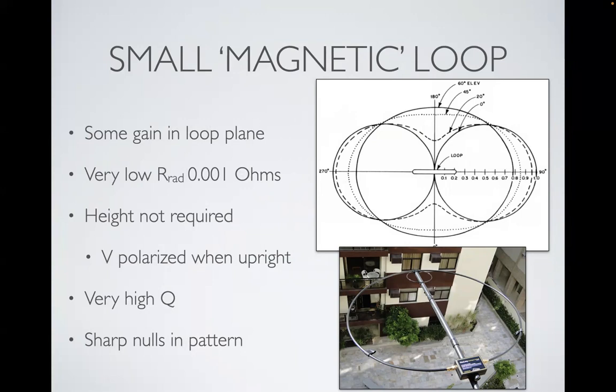If you really want to couple it, you have maybe a loop of copper, or aluminum is a little worse. But copper, and then coupling that into the capacitor that you tune it with can be very problematic. And you probably want to silver solder it because you need the resistance to be that low. And for that antenna there, what is that called? The Alex loop. Poor Alex just passed away recently, didn't he? But I have one of those. And the resistance of those PL259s there can be an issue. And he did provide plated ones, so it's not as bad as the usual sort of tin plated ones.